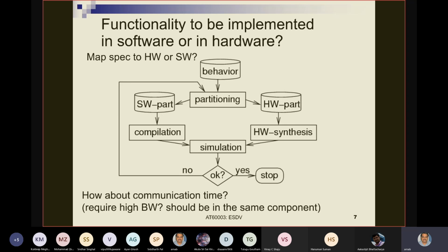However, we must understand that hardware execution is much more performance efficient and energy efficient. Why? Because you have a customized circuit which performs only that functionality, against software execution, for which you have designed a machine code. For that machine code, you will essentially have micro operations, and for those micro operations you will have hardware functional units, with only a limited number of them.